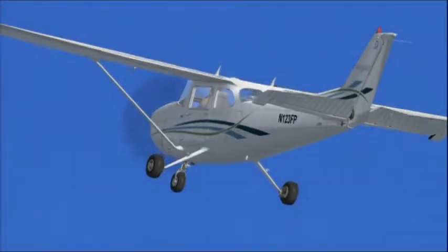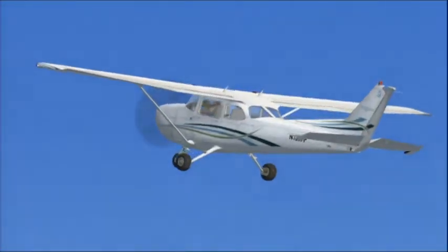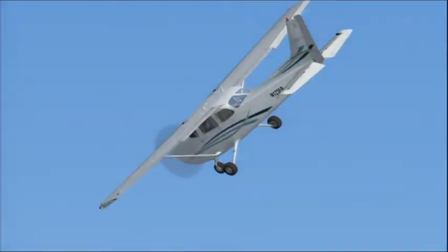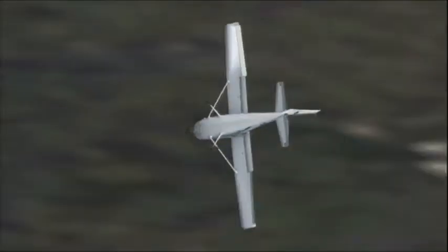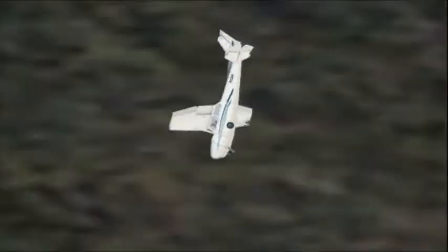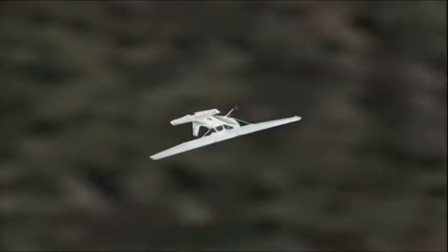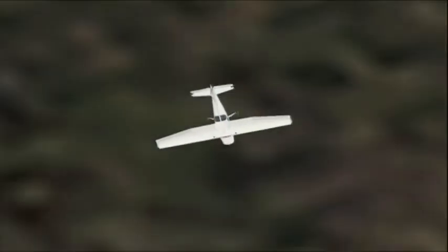But the big difference is, usually because the airplane is in a yaw, the stall is much more abrupt, happens much faster, and you'll typically feel a wing drop, either the left or the right. And so you'll feel what feels like a roll. It's really a consequence of the yaw. But the airplane suddenly, the wing drops, the nose pitches down, and it's a much faster, more aggressive type feeling or reaction of the airplane than you would in a normal training stall.